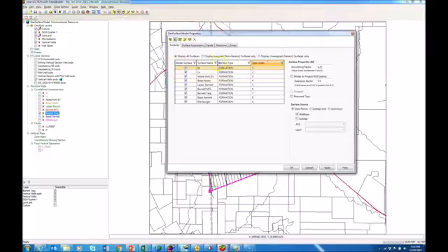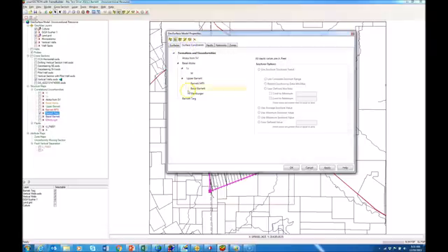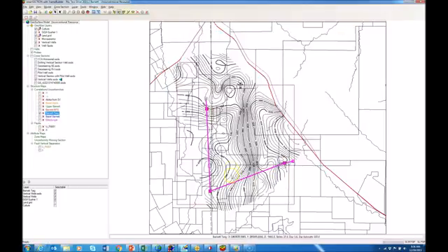Now if I go into the geosurface model properties and interact with Frame Builder and put the target surface in its correct stratigraphic position within the hierarchy of conformance and let it model on through, you'll see now that we're conforming to the basal Atoka, and this target surface is now filled out over a larger area.